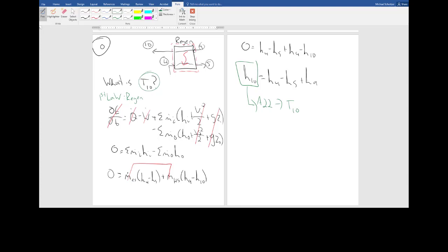But you just go to the next place where you have a temperature, and then you come down through the turbines. Once you have that, then you can go back and fix state 5 once we had state 9, right? So 9 gave us 5. You can tell when I'm doing this with the mouse. Hopefully that looks worse than when I do it with the pen. And then you can do the first law on the regenerator to get the exit temperature or the exhaust temperature.